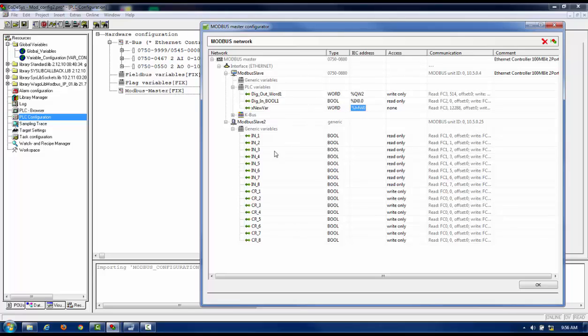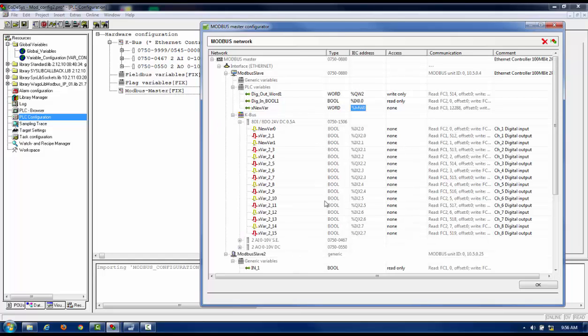But I just wanted to show you that as well, that it's not just, well, I have to scan it, and what if I want to write to some register in here, but I don't have write access directly to these specific Modbus registers because it is a controller. And of course, if it's a controller running its own executable code, you're not going to have direct write access, if you will, to the outputs. The PLC itself will have that. So again, just wanted to point that out as well, some other things you can do in here.